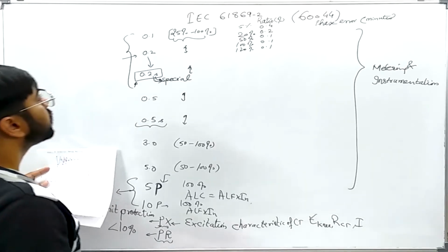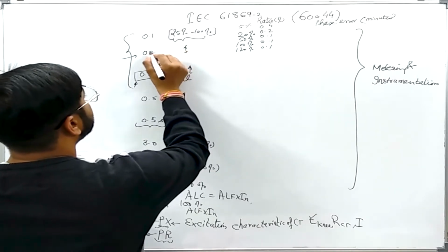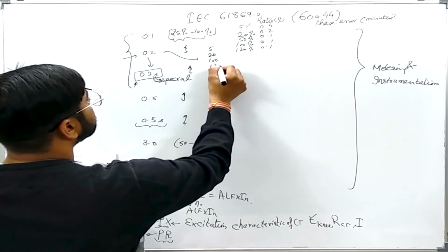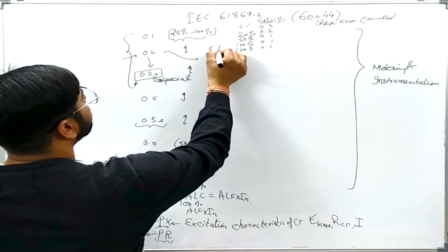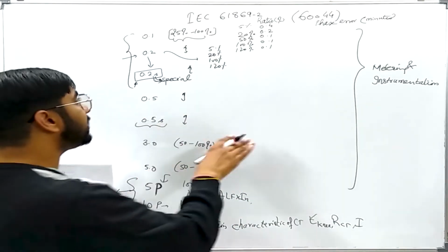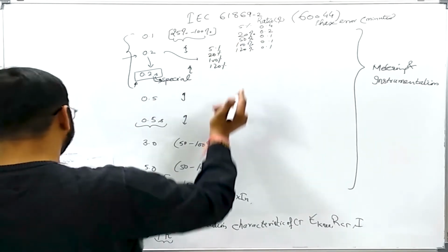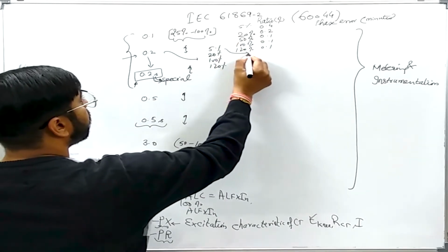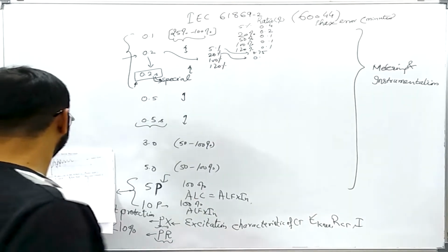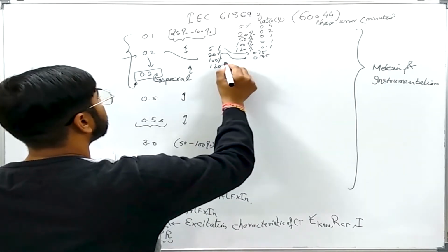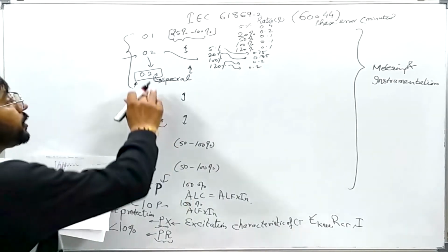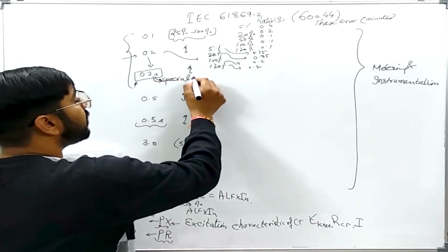Okay, now similarly for 0.2 class CT, 5%, 20%, 100% and 120% rated load, the error will be the guaranteed error, that is error will be less than the guaranteed one on these currents will be 0.75%, 0.35%, 0.2% and 0.2%. Okay, for the 0.2 special class the error will be little lower.